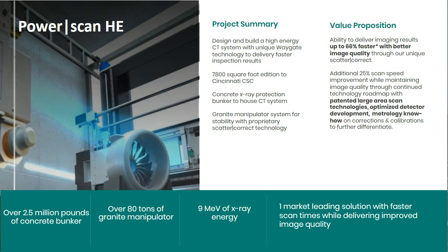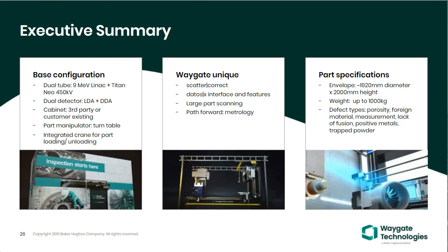We really looked to use our scatter correct technology and some of our core technologies from our other products to bring access and availability of this type of technology to the industry, and to work on getting scan times for these components down to acceptable production levels. So the system we built here for ourselves is available for services, and we're also interested in helping people build their own as well. It has a 9 MeV Linac. It's got a Titan 450 kV source.